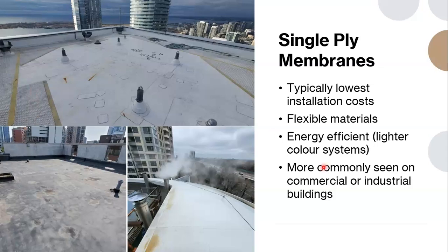We also often see paving stones installed as a walkway to various roof areas. However, it's important to note that if you're putting paving stones down on a single ply roof system, it is imperative that there's insulation underneath to, again, protect the membrane.